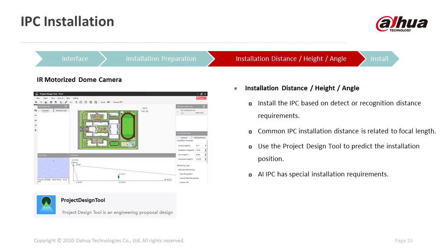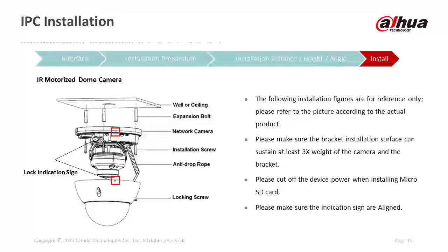Use the project design tool to predict the installation position. For the installation of the dome camera, please refer to the picture according to the actual product. When installing the shield, make sure the indication signs are aligned.